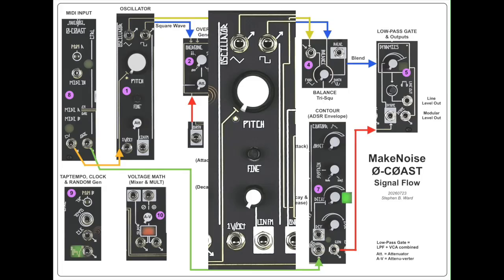In addition to that, there's a linear frequency modulation input, which allows for FM synthesis, LFOs, or pitch envelopes, depending on the kind of signal that you plug into it. Now, it has a dedicated attenuator that lets you control the depth of the FM effect.